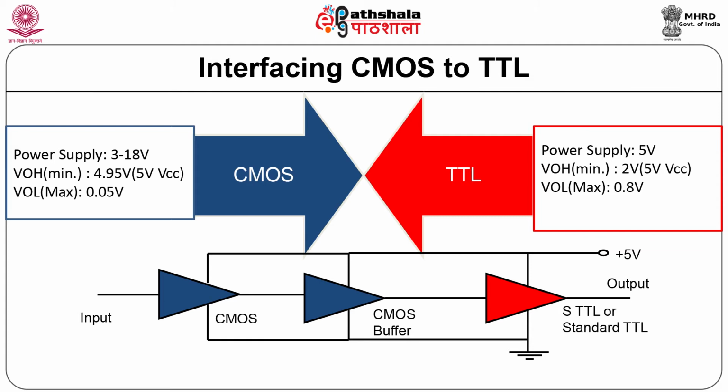In CMOS to TTL interface, with the two devices operating on the same VCC, one can have voltage level compatibility, but current level compatibility must be considered. That is, in the low state, the output current sinking capability of the CMOS IC in question must at least equal the input current sinking requirement of the TTL IC being driven.